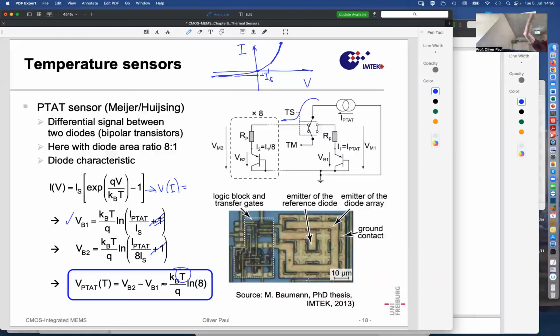And the average of an inclined slope is equal to the value in the center. That's a common centroid approach of circuit design. It's just a manifestation of Taylor series and elimination of terms of the Taylor series. What is added on one side is subtracted on the other side, and so on in all directions.